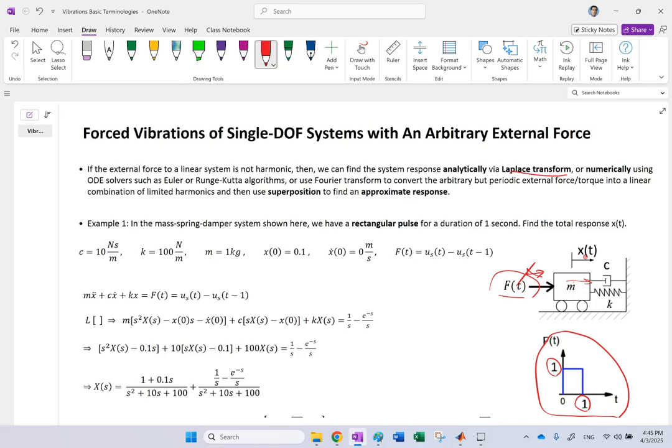You're going to see a little bit of oscillation, but there is damping in the system and there is no more energy injected into the system after 1 second. Therefore, that damper will very quickly dissipate the energy and the vibration of the system will stop. So you should see some short duration vibrations, and that is what logic and common sense say. Now let's see if that's the reality, if we solve for it and simulate it in MATLAB.